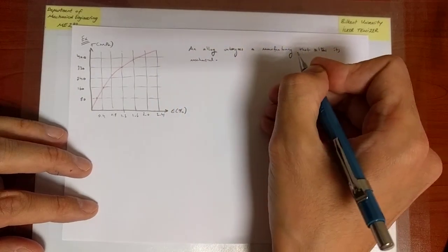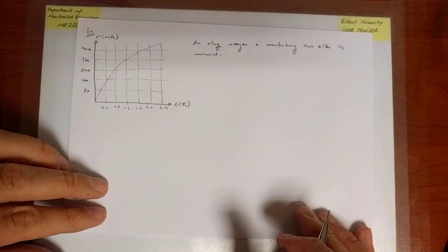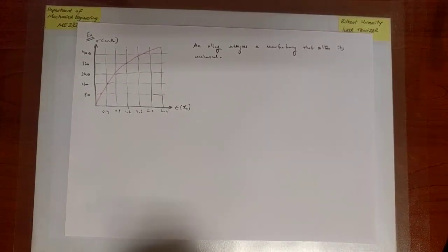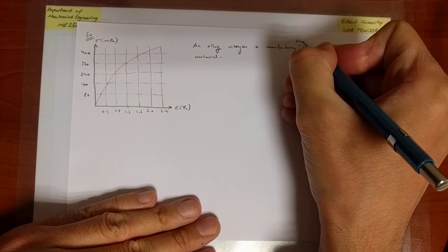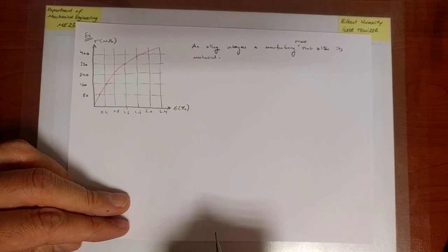If the manufacturing process involves deformations, we know, for instance, that the yield strength, the ductility of the material is going to change with deformation. It will significantly harden, etc. We've discussed these before, and therefore, as soon as the material undergoes this manufacturing process, then its properties will change, and I need to somehow determine the new properties.